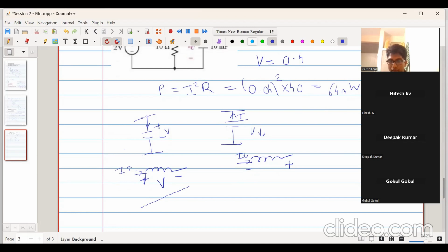But when we change the polarity of the voltage, the inductor current will start reducing. You must remember that the inductor current could still remain positive. Like it could be at 2 ampere, here at 4 ampere, then here at 4 ampere, here at 2 ampere. So the direction of inductor current has not changed, but the direction of the voltage applied across the inductor has changed.